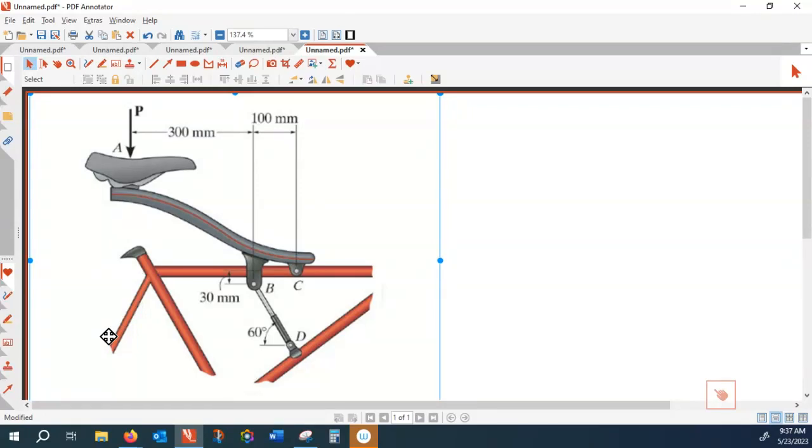But with the BD, that's a telescopic arm. Telescopic can get shorter and longer. It won't bend. If a telescopic arm bends, that's a wrong design. Telescopic is a hydraulic system, only designed to take the axial load. So why is that important? Beam or bar, why should we care? BD being a bar, a bar is a two-force member. It can only take force in an axial direction.